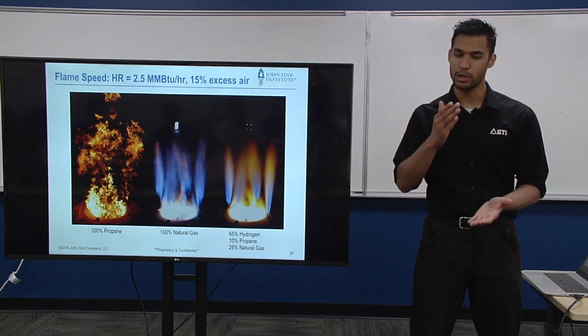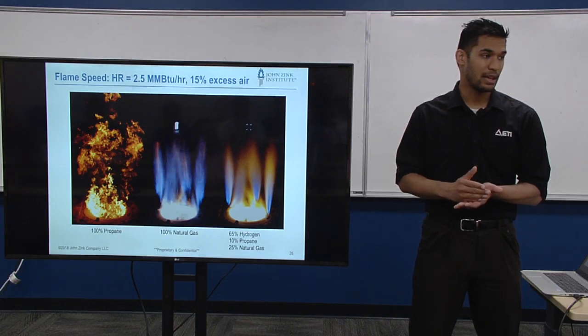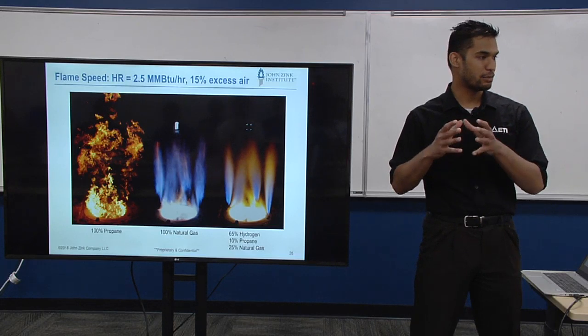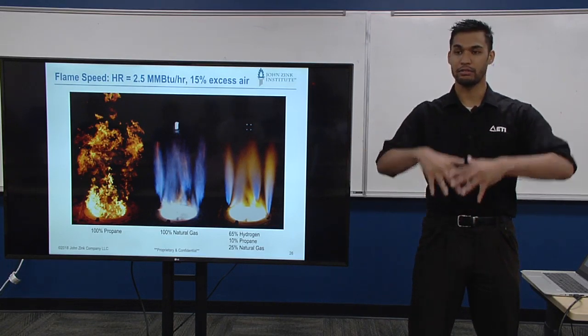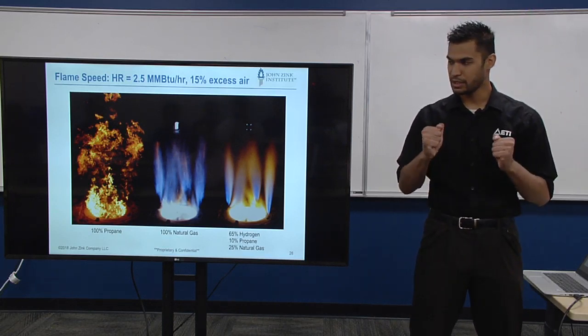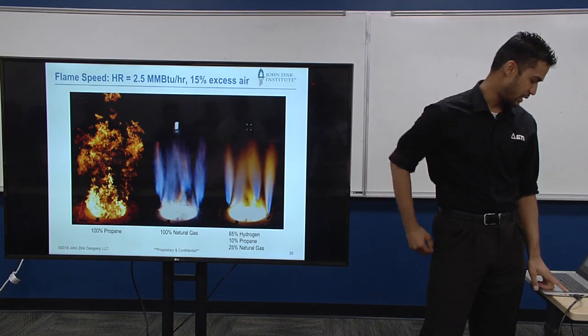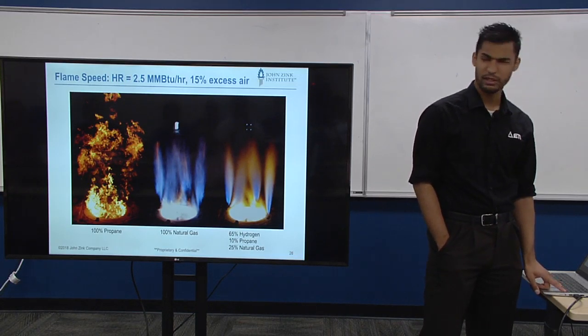You want to look for, oftentimes, symmetry, right? And it should stay steady. If everything's tuned correctly, it should be steady. The flame should not be moving in and out and lifting off and coming back down. You want things to be nice and stable and steady. So that's the biggest visual indicator I like to look for when I'm analyzing, or if I'm out in the field looking at burners or any combustion equipment.